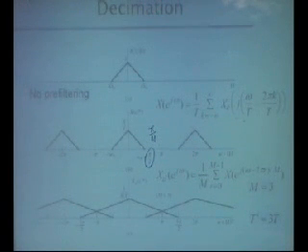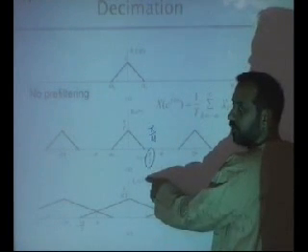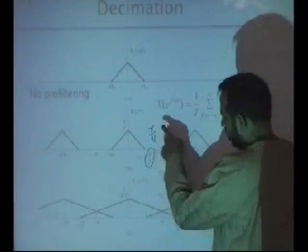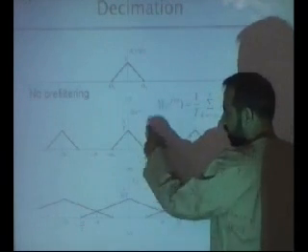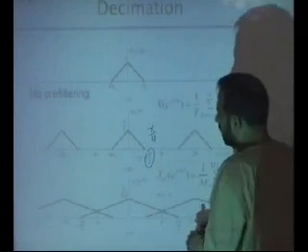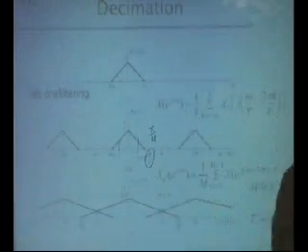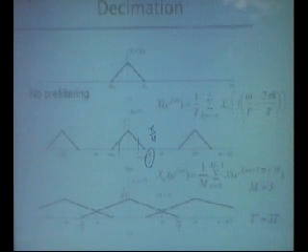The other way is, if I really intend to throw away samples, then I need to make sure that first I cut down my digital frequency to pi by m, in this case pi by 3. I need to pass it through a low pass filter.